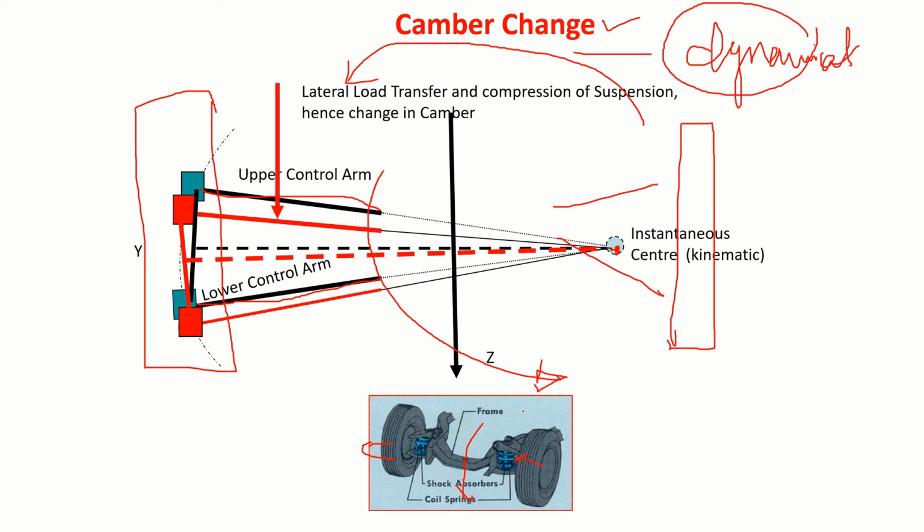The moment you change the camber, if there is too much camber change, what is going to happen? There is going to be a larger lateral force on this side and a smaller lateral force on this side. There is a chance the vehicle will start pulling to that side.